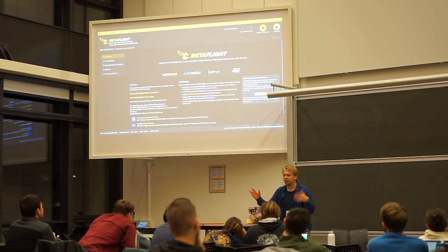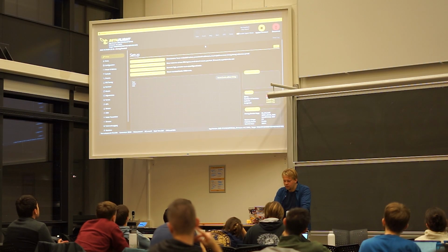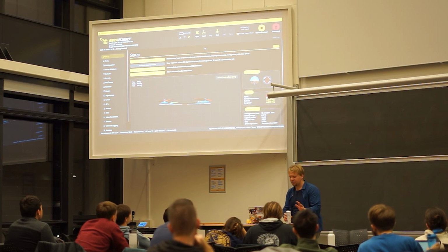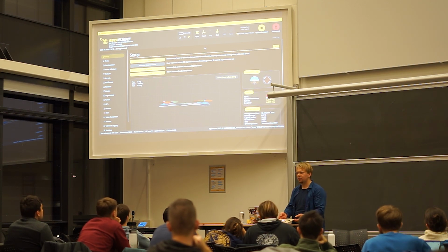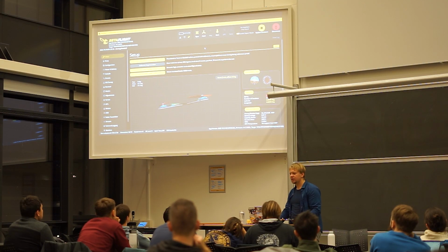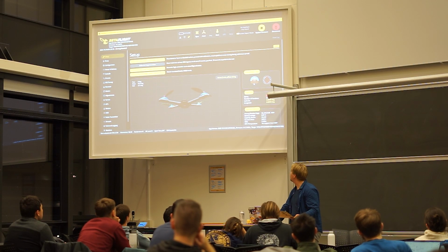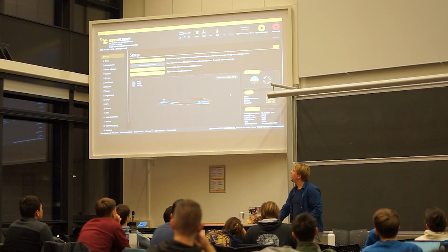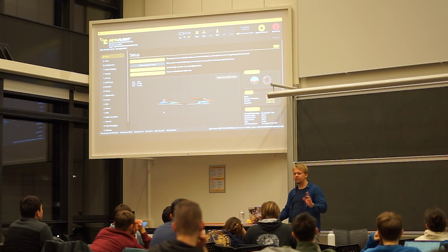Let's replug it, and I'll show you the configuration, kind of how it works. So now you can see that the thing is connected. You check if it's actually connected: you move the drone itself, and you have a visual indication of the thing that moves. This one shows you the z-axis. This one I don't know why, and this just shows you the wrong y-axis. Now that's all just an accelerometer in general, combined together.